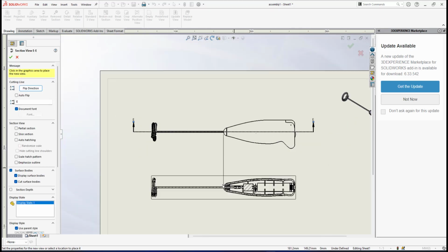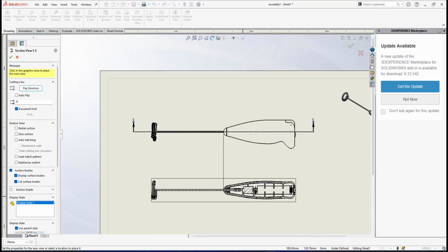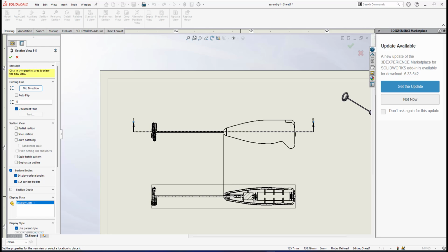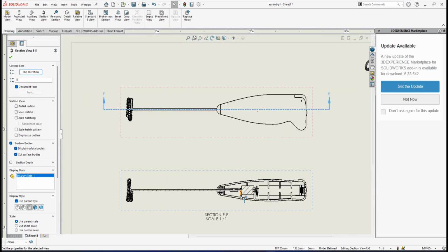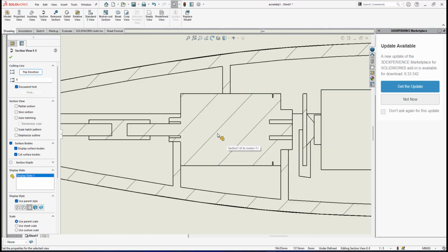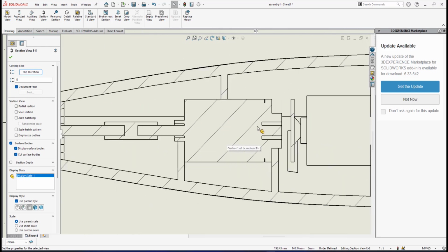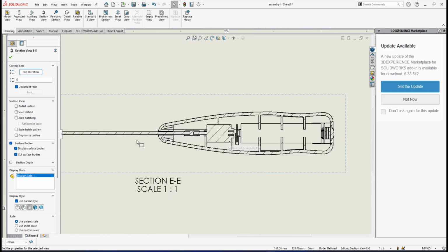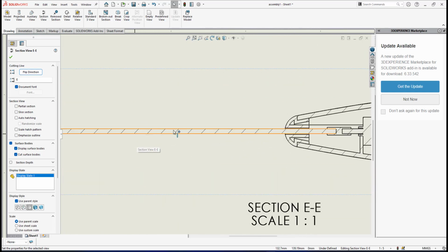And now Solidworks puts in the section view. I will bring my section view to the bottom here, so my front view will be my section view. As you can see here, components like the DC motor are hatched, because Solidworks cannot figure it out. For example, this long rod, the shaft, looks weird when hatched. So I also need to remove them from the hatching.